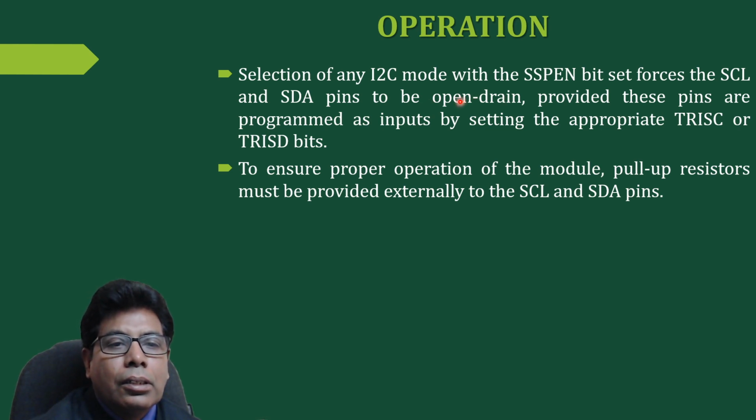So if these pins are not programmed as input by setting the appropriate TRISC or TRISB or TRISD, these are different ports which have the data direction registers TRISC, TRISD, and TRISB.